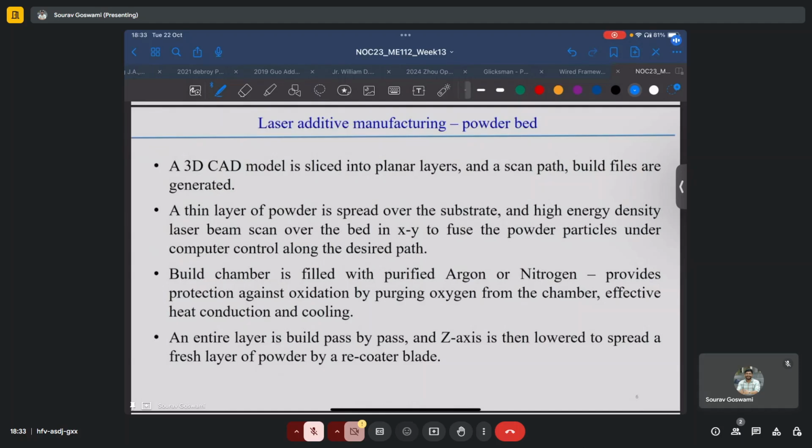During the course of our discussion, we also looked at how the recoater may either have a blade-like morphology or it can be a roller, or it may be a frog feeder, or in certain cases it may also be an electromagnetic recoater. And we also checked what advantages each of these types offer.